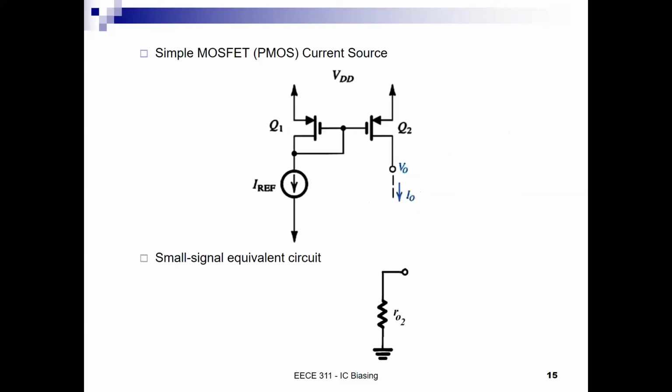Great. Let us now look at the same circuit implementation, but this time in BJT. Now we used a PMOS with PMOS, or NMOS with NMOS, but what happens if we use NMOS with PMOS? The mirroring requires sharing the same VGS and sharing the same VOV. So for the same current equations to be governed, since it's a mirror, it has to be symmetric, right?